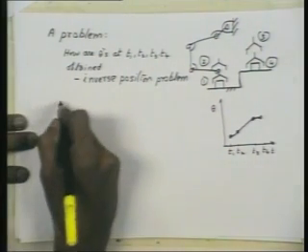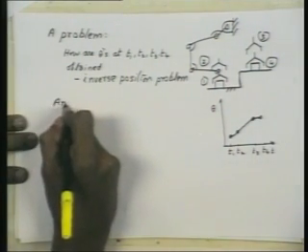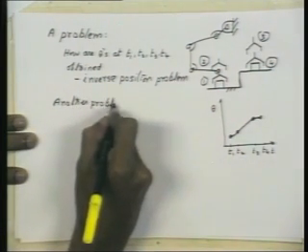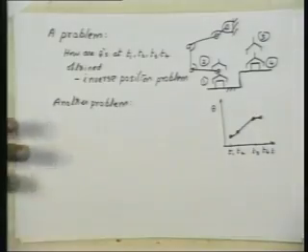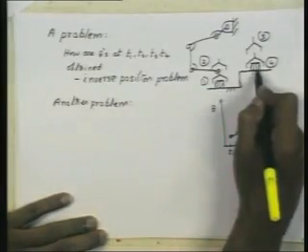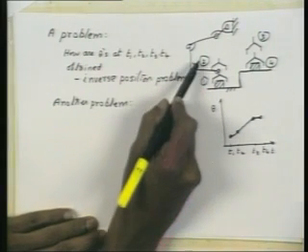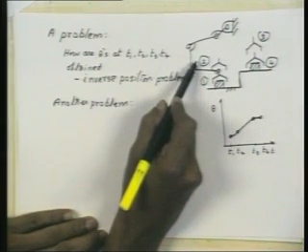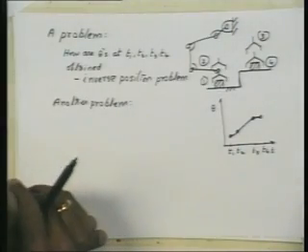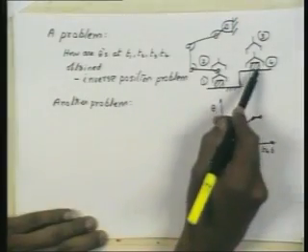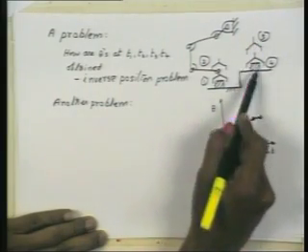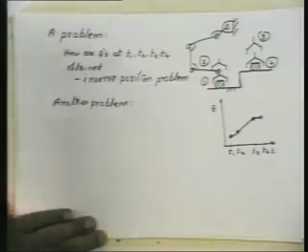Now consider another problem. If you remember, we had taken it to position 1 to 2 to ensure that it doesn't collide with the table or the surface on which the block is kept, right? And immediately before putting it at 4, we had specified a position 3 to ensure that it doesn't dig into the table when it places something.